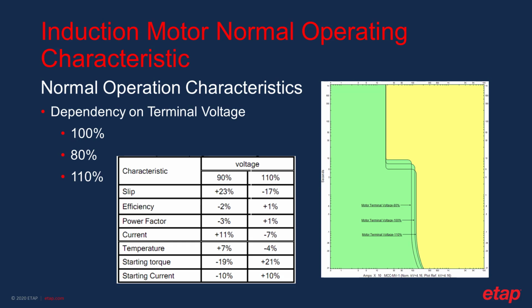This means that if you have a 10% voltage drop, or your voltage is at 90% of nominal voltage, the actual starting torque of the motor would be reduced by the square of this amount, which would be 81%, equivalent to a 19% torque drop. A drop in the starting torque means the motor would have less acceleration torque because the load torque remains the same. So the starting time for the lower voltage would be higher, as you can see, or longer.